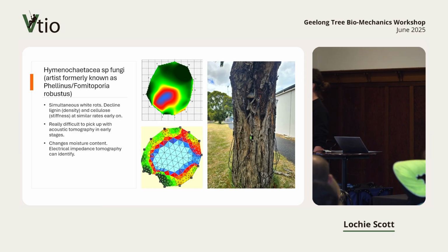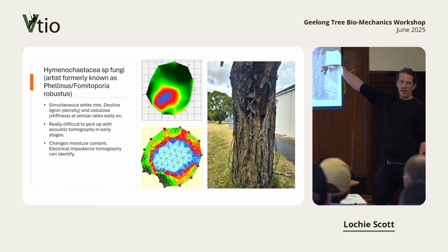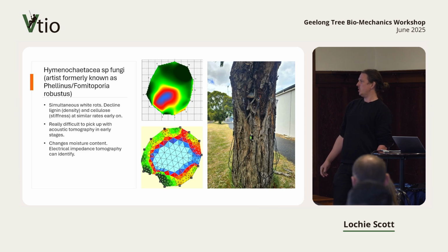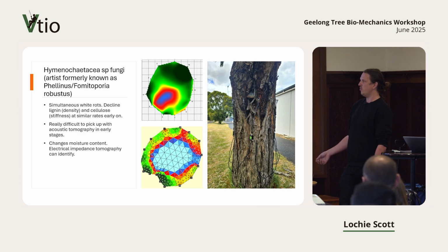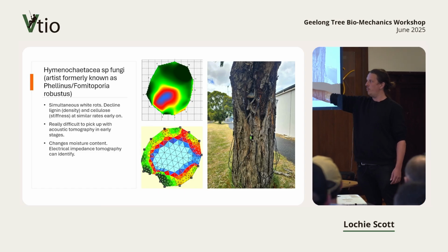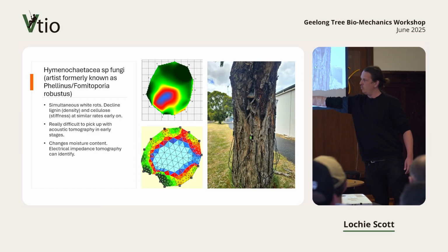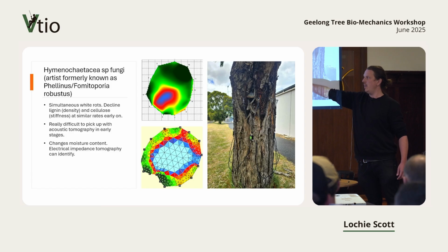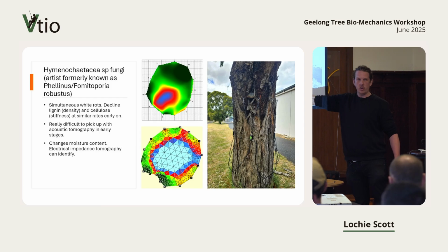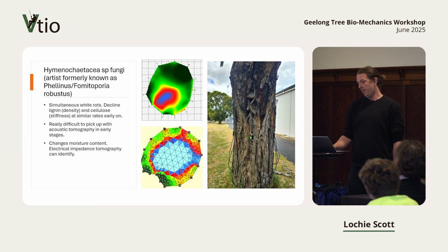You can kind of see I got the very edges of it here. Along the edge, there was some sort of visible decay right on the outside. I suspect some sapwood, but in those cases, where you suspect you've got an infection of that, sometimes sonic tomography isn't the most suitable piece of kit, and I had to move to an electrical resistance tomograph, which is very hard to interpret. But around the outside here we can see this whole area would be showing as green if it matched the tomograph, but we're showing this large amount of sapwood dysfunction on the outsides there. So yeah, just to know that we can't identify everything with it too.